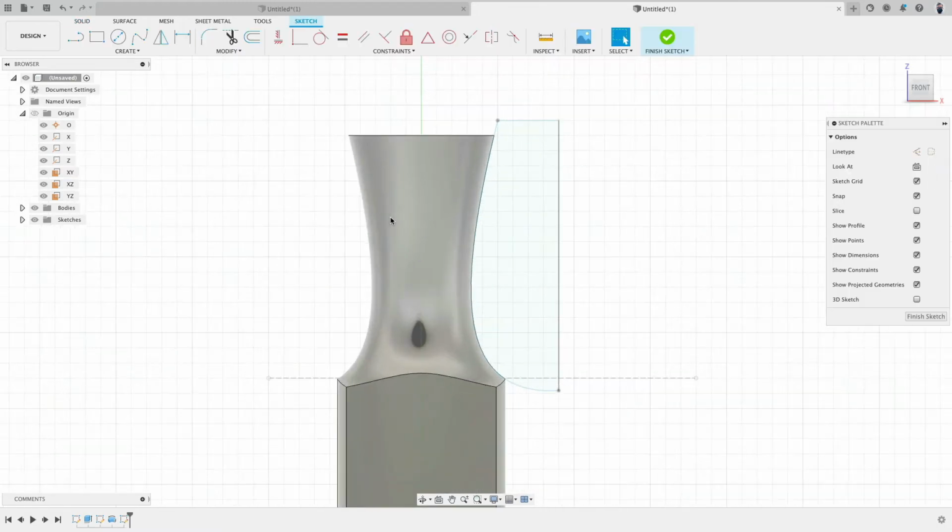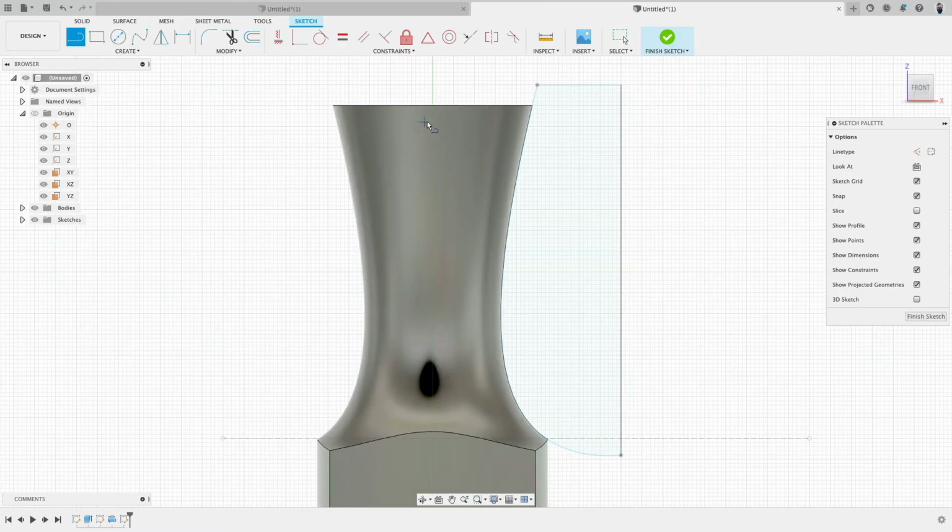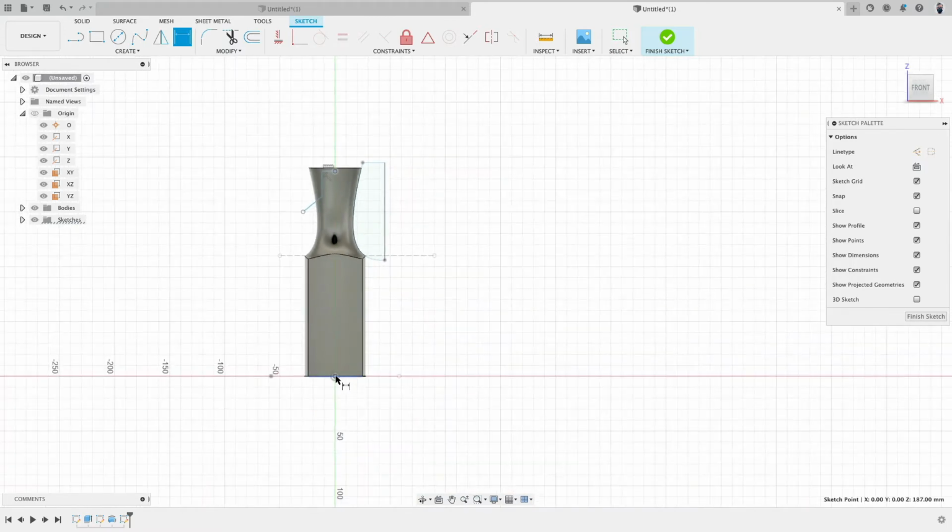So click on this plane. And to make it visually easier, I will start doing this down here on the left side. Right side is this cut, left side is this part. D for dimension. 190 is the height, I know that.